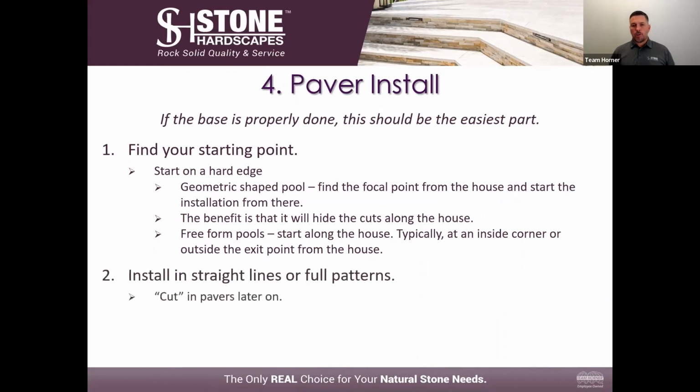When you're installing the pavers themselves, you need to install on a straight line. Don't try to cut as you install in straight lines. This allows you the most effective and efficient way to install the pavers. Now, a typical install crew will have 5 to 7 people there installing.